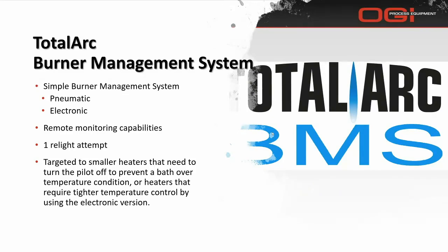Additionally, another target of these controllers is areas that require much tighter temperature control. As we know, pneumatic controllers have quite a wide deadband on controls. And so with the TotalArc BMS, an electronic version of it, we can actually use a thermocouple and specify, down to 1/4 of a degree, what is your set point that you want to control these heaters.